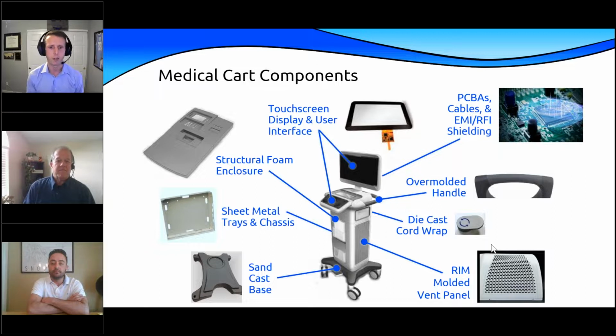Fairly basic fabricated component, but it's got some complex weld requirements. And whenever you're dealing with high cosmetic requirements of medical devices, anytime you have welds or assembly, a lot of touch points on a part in manufacturing, you really have to manage the cosmetics of it and plan for the cosmetic finish that's going to be applied. And that's what we did here, so that the tray here is a nice cosmetic match with the rest of the cart.